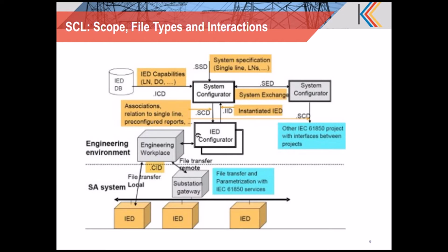Instead of using the direct ICD, which is a superset of IED capability, there can be an Instantiated IED Description file, which can be a subset of the ICD and is actually used in the substation, and which can be used by the system configuration to create an SCD file.